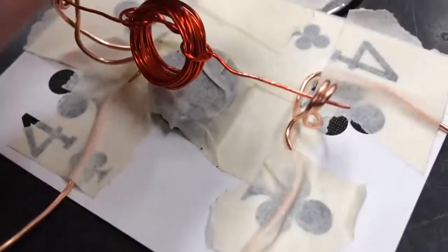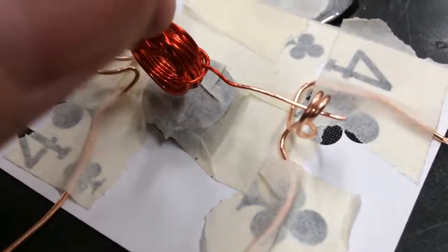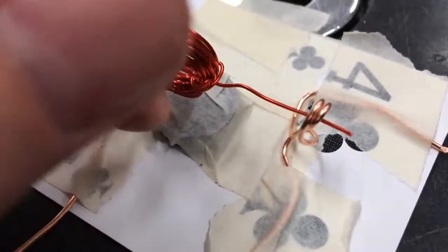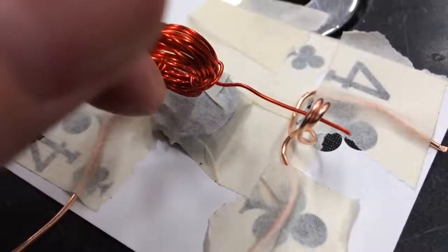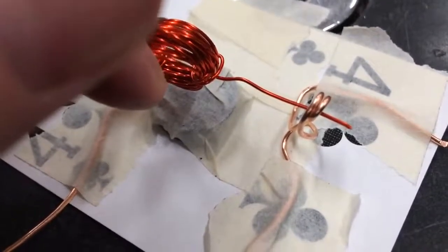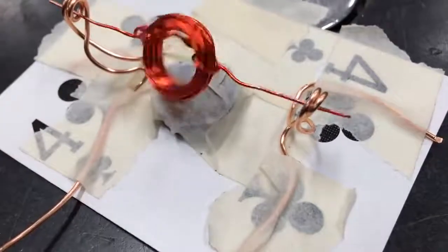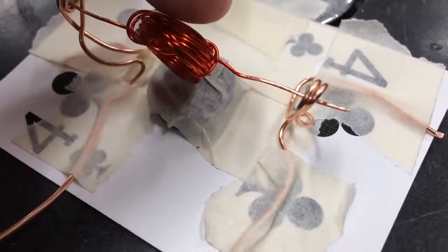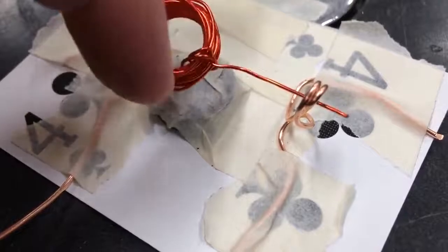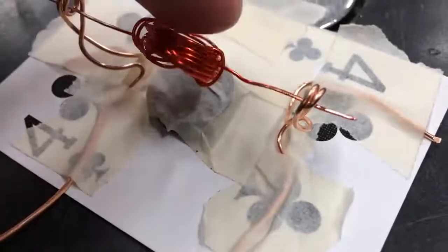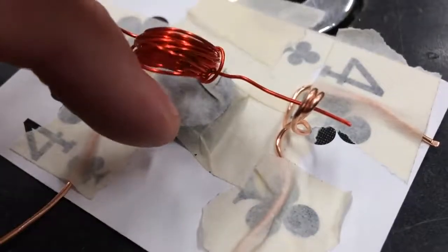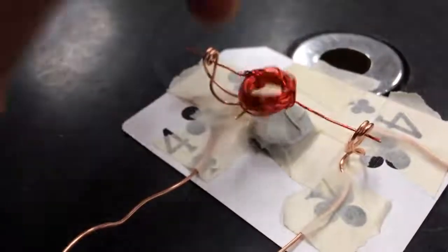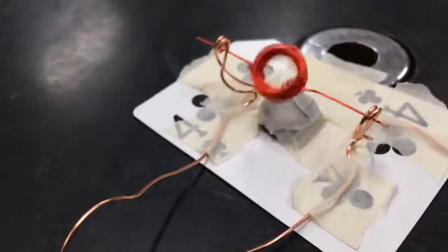If we spin the motor, you can see that half of the enamel's been rubbed away, but the other half is still there. And that means that when the motor's like this, the copper wires are touching and electricity's flowing. But when it's like this, the supports are touching the paint and electricity's not flowing. So in this state, it's actually turned off. But when I flip it over, it turns on. So our motor's only on for half the time. When I give the loop of wire a little kick, it keeps going.